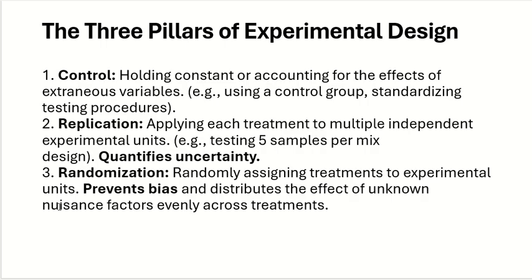For example, somebody took fibers because people are getting good results for tensile strength. Now they are putting the fibers in the concrete, but they don't have a control sample. So they will never know that fibers can actually reduce the compressive strength of concrete. Without the control sample, you will only compare between the fibers themselves. Lulwa will say I am using bamboo fibers, and you come in and say I am using steel fibers, and you are comparing between them.